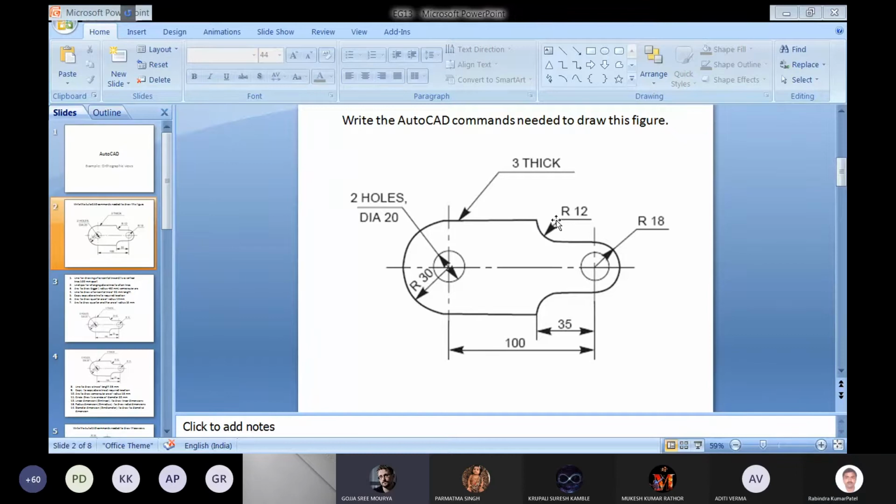First endpoint, two inputs, X and Y, another one X and Y, and R in the command line, in the form of points. Otherwise, we can directly select the points by using the snap command. So we can select the endpoints, and where a radius is required, you can put the value 12. Otherwise, yes, you have to provide the coordinates of these points and the radius. Okay, sir. Thank you, sir.